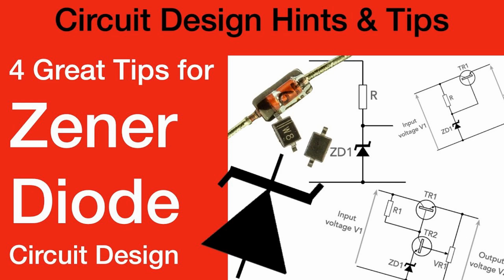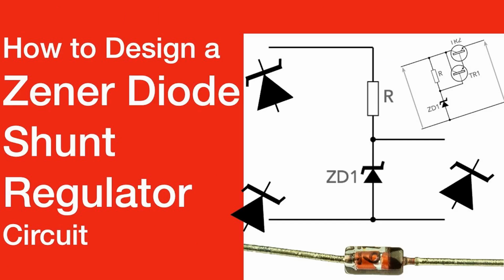3. Signal clipping circuit. A signal clipping circuit limits the voltage of an AC signal to prevent it from exceeding a specified range. Components: 2 Zener diodes, VZ. Design steps. Choose Zener diodes. Select Zener diodes with a Zener voltage, VZ, equal to the desired clipping level. Example: for clipping at plus or minus 5V, choose 2 Zener diodes with VZ equal to 5V. Connect the Zener diodes in series, but in opposite polarity across the signal source. When the signal voltage exceeds plus or minus 5V, the respective Zener diode conducts, clipping the signal to plus or minus 5V.